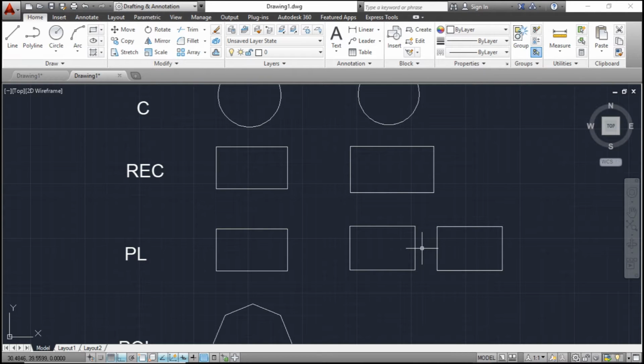The difference is that a polyline is composed of grouped lines, while a rectangle made of lines is ungrouped. See the difference? You will have to click all of it before the entire region is selected, while in a polyline, you just have to click anywhere and the entire region will be selected. This one, the polyline, is grouped and the line is ungrouped. So that's it. You don't have to do this one.